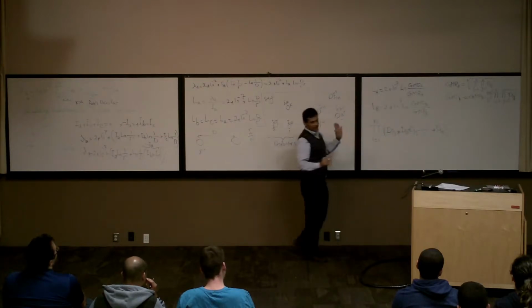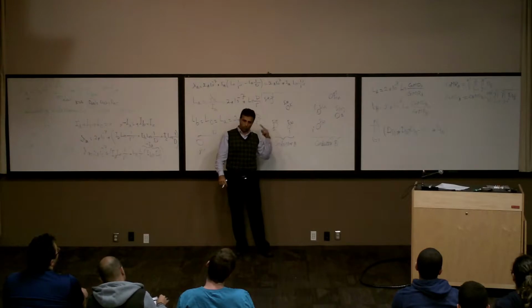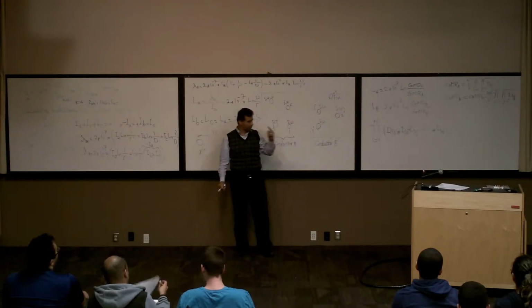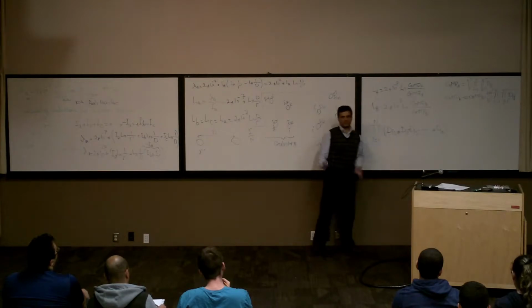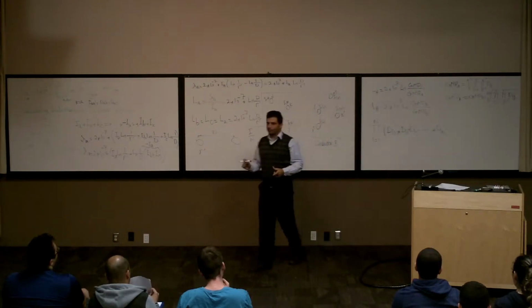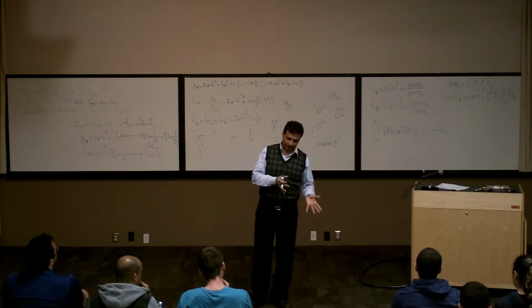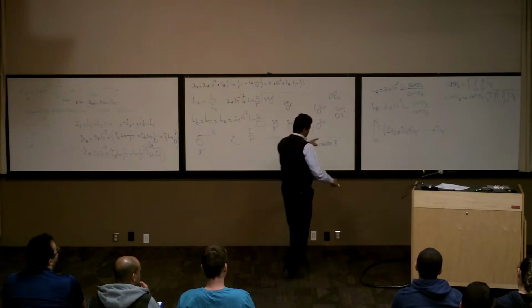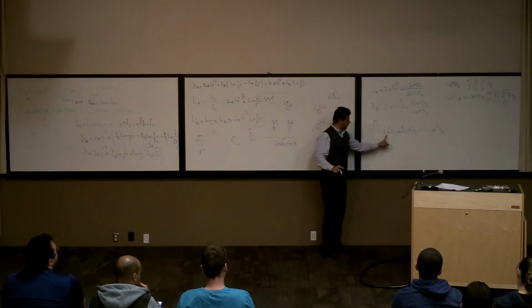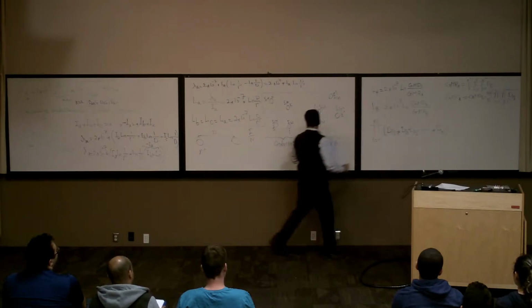And we change the j from 1 to n, right? Now let's go for only one term. If I put i=1, it's going to be D11. What's D11? R prime, right? D11 means the distance of the conductor with itself. It's going to be R prime, right? Now, look at here. It's going to be for i equal 1: D11, D12, D13, D1n.